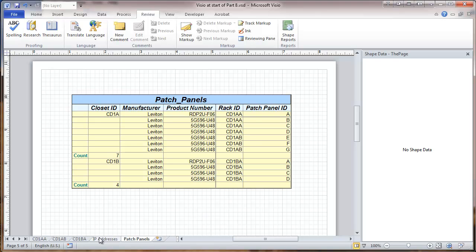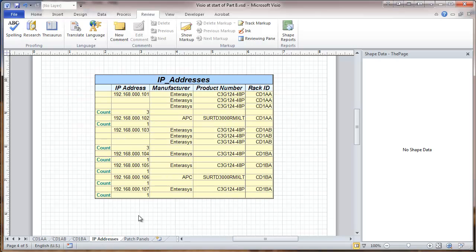Basically, that's it for generating equipment schedules. It can be done with other types of equipment. It's particularly effective for these where you want to correct errors on the report, but it's also useful in terms of ordering materials, in which case you might want to list switches, and you could group them by product number, and that way you have a list and a count take off on how many of them you had. So on a large job, that would be helpful. It will tell you where each one of them was, which rack it was in, that sort of thing.